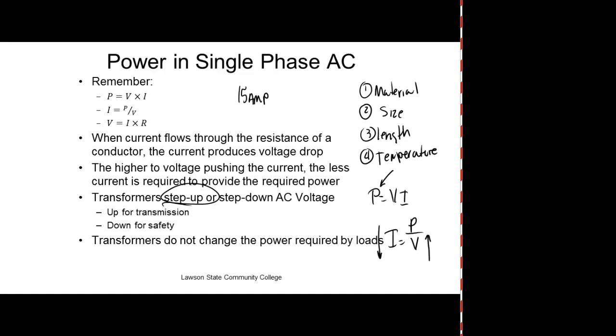It's 15 amps. So 15 amps at 120 volts. How much power could that circuit breaker handle? The power the circuit breaker could handle would be 120 volts times 15 amps. Do the math.